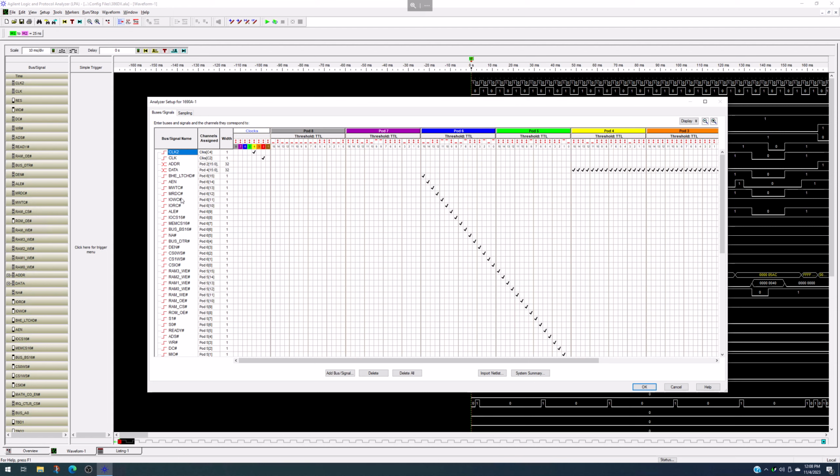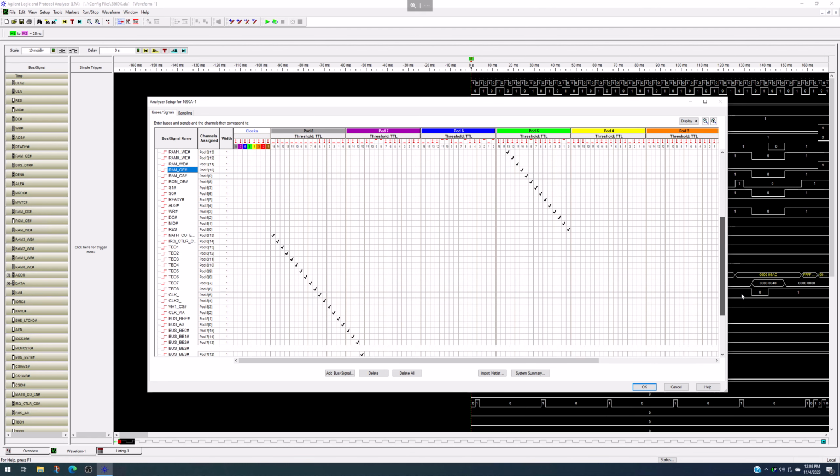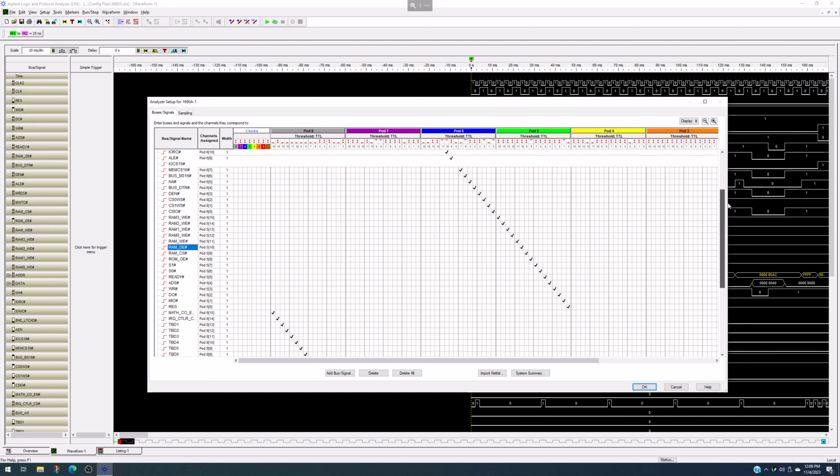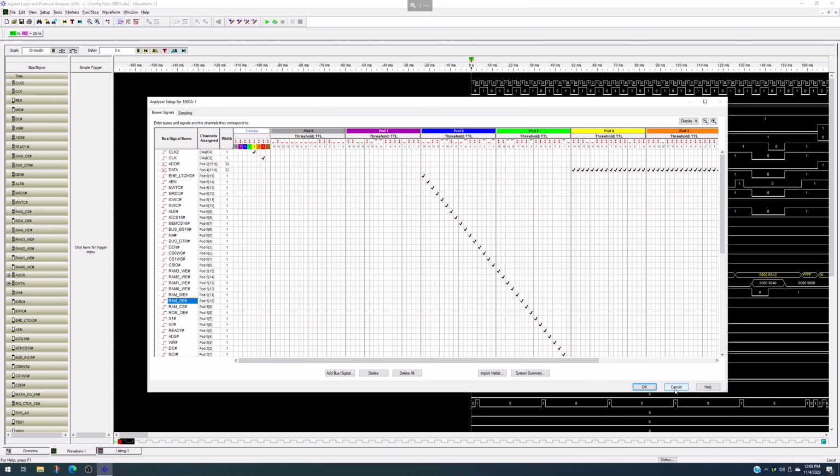But then I've got all of these other control signals, and you can see that I'm going to this next pair, these 32 bits of control, and mapping those, giving them the appropriate names. And then if I go over to the next pair, that's the next 32 bits of signals, some of which I'm not using yet, so I just labeled them TBD. But these are all additional signals, either control signals or just like a pre-latch address. I might use that for some comparison of pre and post latching, that type of thing though. So I've got all these signals that I can now look at and kind of interrogate. Is it working the way I expect it to?